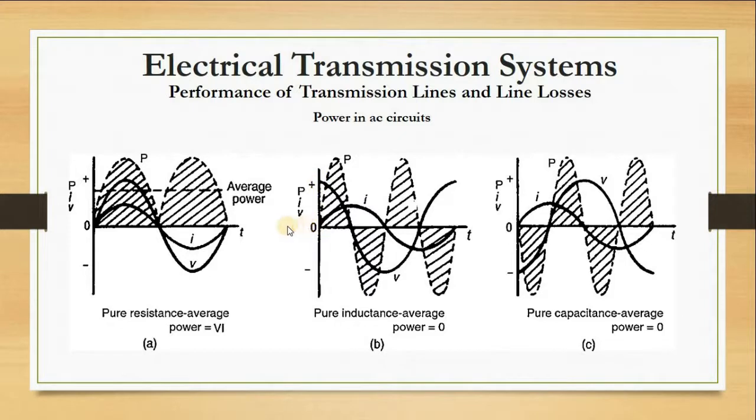So if we project this backwards, it means that the voltage started somewhere here. If you want to bring all of them to the reference point at 0, the voltage may have started from somewhere here. So it covered this distance before the current started. If one full cycle is 360, then from here to here is 180, and from here to here is 90.